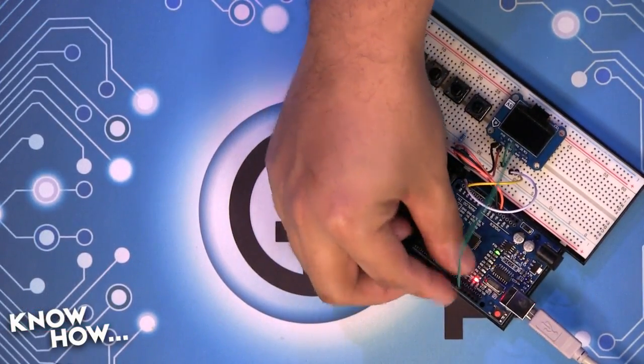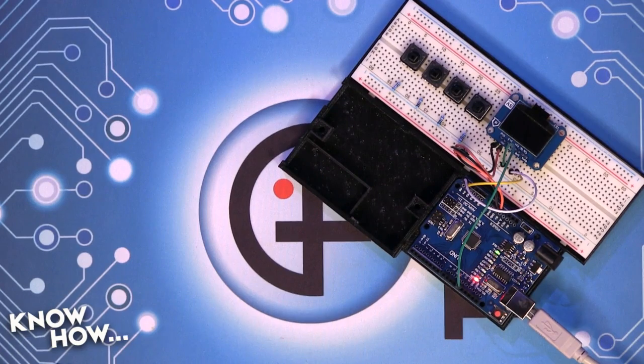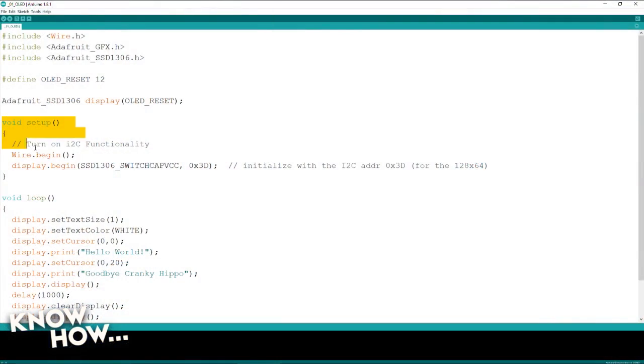So now I've got the reset into pin 12. Go back to my code. My setup is super simple. I'm going to do wire.begin. This is just like serial.begin. All it does is say, hey, turn it on. I know you have the library for it, but let's enable the functionality now, and start it up.